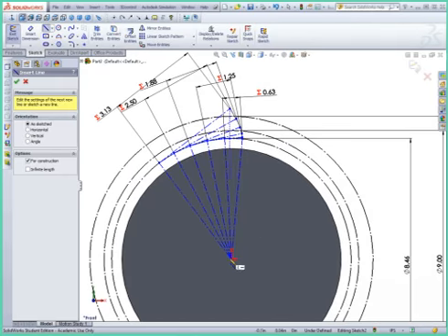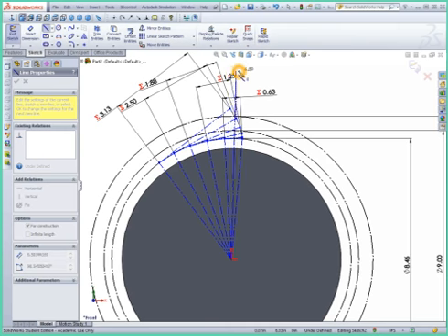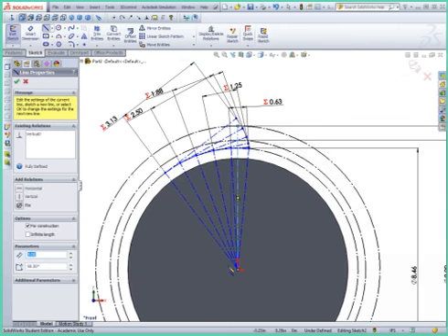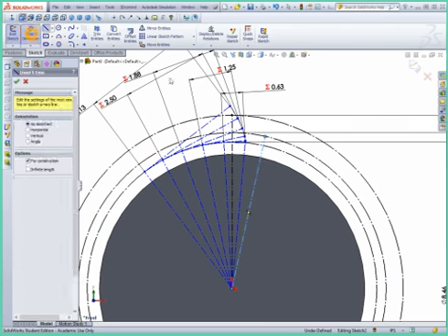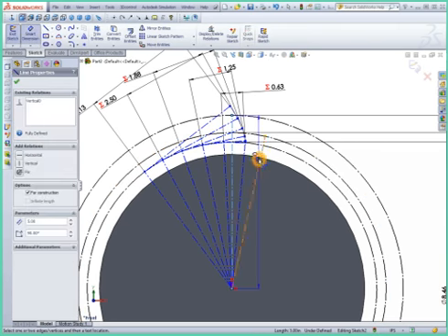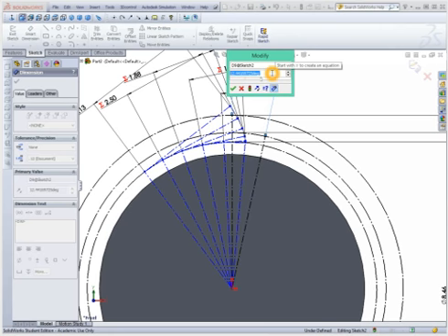And again, I'll make this a sketch line, so it's a construction line. It's not going to actually show up in our final part. And then we need a line that indicates half of the width of a tooth. The key is going to be figuring out what this angle here is. The relationship is actually fairly simple: the sector length is equal to the radius times the angle in radians. We're going to be working in degrees, so that's not too difficult to convert back and forth.